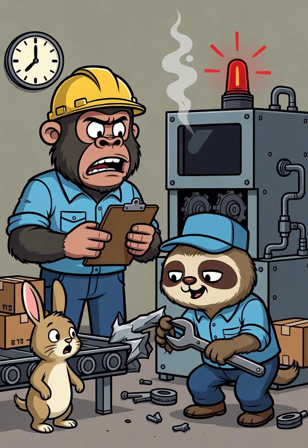The machine physically could not run. Now later in the day, we had to switch from making blue widgets to red widgets. That changeover took 25 minutes. Again, the machine is stopped. More availability loss. Then at 2 p.m., we ran out of raw material because the supplier delivery was late. The machine sat idle for 40 minutes waiting.